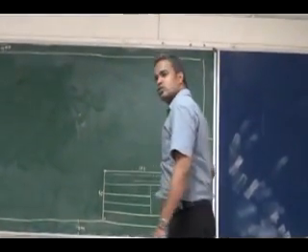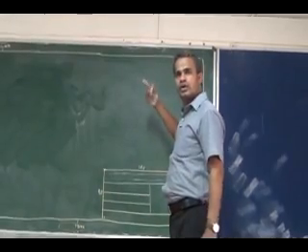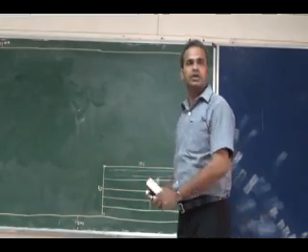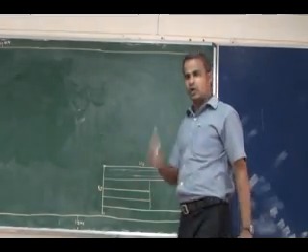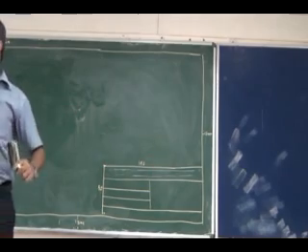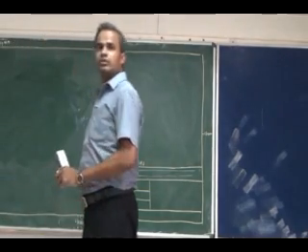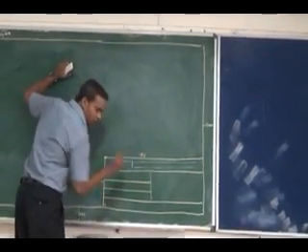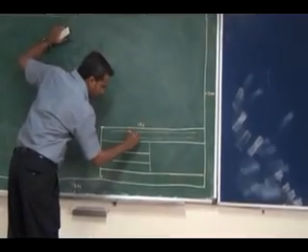This should be drawn using your drafter, which you will have in your instruments, you will see. Using the drafter you have to draw 2 parallel lines, so that it is visible for you. Now in your drawing sheet, this parallel line should not be visible. If I come and see your drawing sheet, it should not be visible. Just whatever matter you are writing in those two parallel lines, that alone should be visible. It is just for the straightness of writing that I am drawing two parallel lines. Here you can write the name of the drawing, not your name, otherwise you can write the topic.